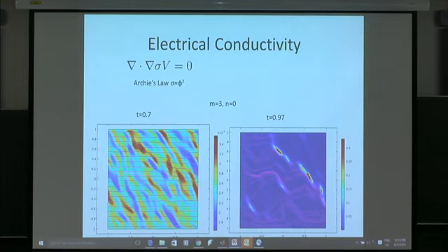So these pink lines now are showing streamlines of the electrical current density. Okay, and so again, for most of the evolution of these things, they're just starting to deviate a little bit from just being straight lines going straight across. By the very end of this simulation, you can see that the streamlines have deflected significantly, and the current wants to be in these high conductivity bands. And I should point out, to get the conductivity, I assume Archie's law. Okay, so that the conductivity is just proportional to, in this case, porosity to the power 2.